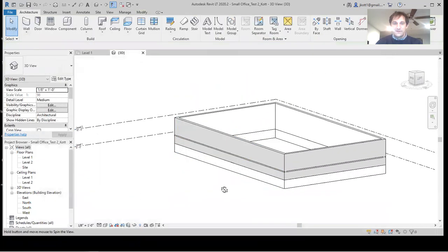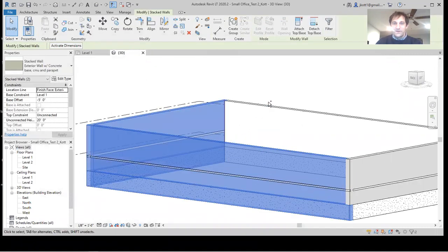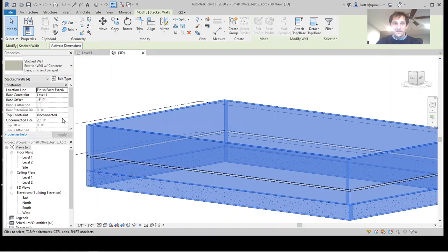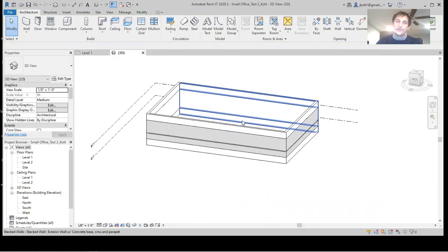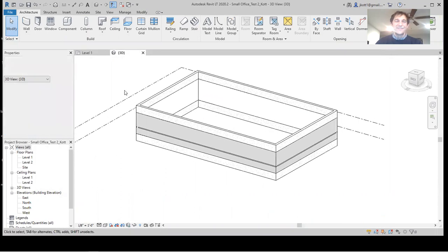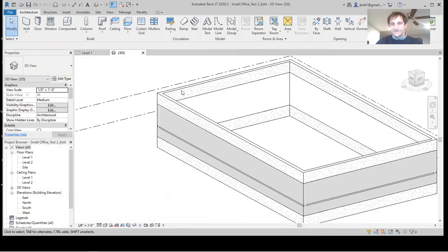And now you get that. The reason it's not showing the top of our wall is because the wall's not tall enough. So if we make it taller to 25 feet, now we're showing our parapet as well. Parapet, say it the right way. So anyway, basically that's the exterior of your building.